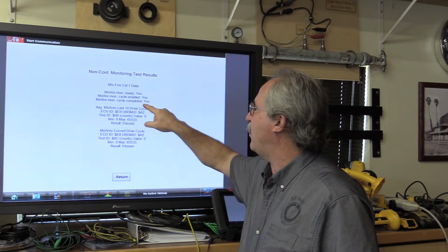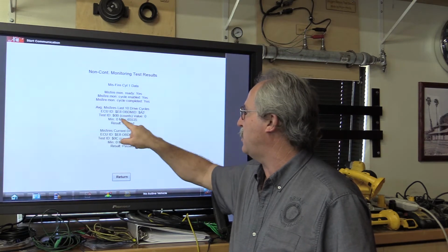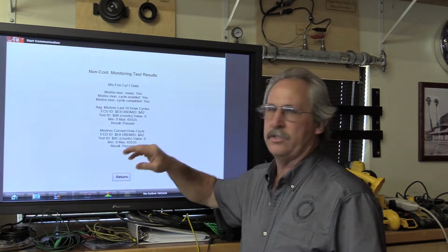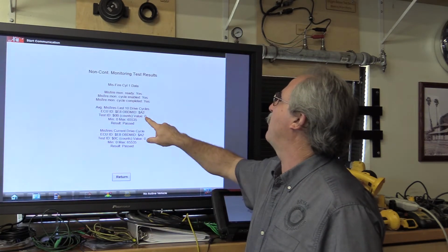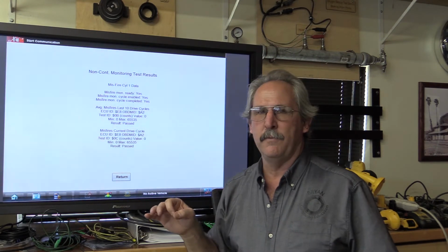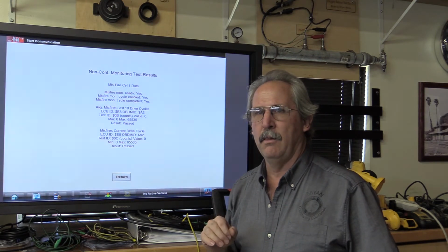It's telling me up here, but not all cars or all scan tools will tell me that. I need to understand if I see all zeros, it hasn't tested it. If I see a 0 and a max number on CAN vehicles, it's run the test. The other number I want to look at is this number right here. And what I can tell you is, if that number is not 0, you have a misfire.